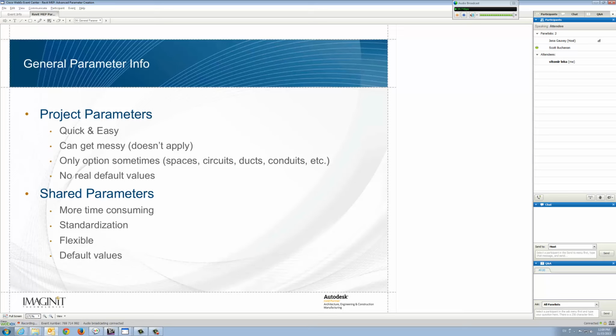So we don't run into the issue we saw with mechanical equipment. I could go directly into pumps and attach horsepower and not have it get assigned to a VAV box. That makes it much more flexible at the parameter assignment level. And there are some utilities from Autodesk that help you push out mass shared parameters, and also to multiple families if you want.